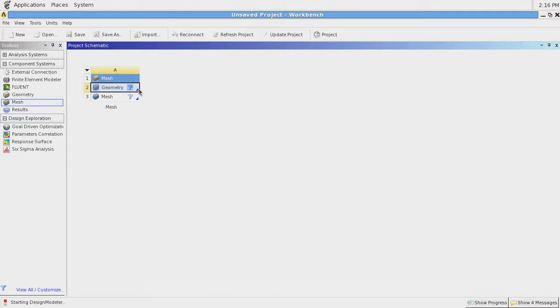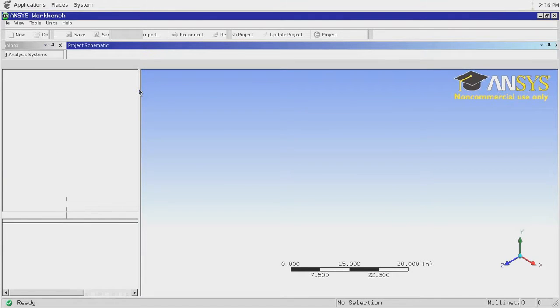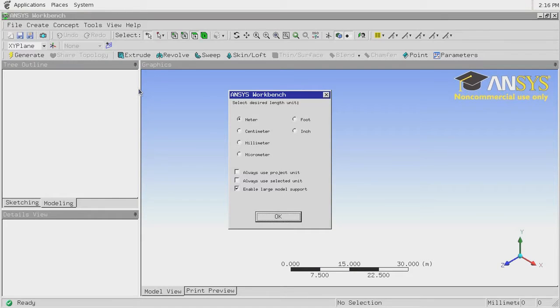I'll have to tell you from now that in CFD analysis there are so many methods that you can use in order to simulate a case. In your case, LES method is the best method that can be used, but the problem with it is that it consumes a lot of time. It requires really a long time to get you an answer or a solution, and it requires high computer performance levels and high memory and multiple processors.